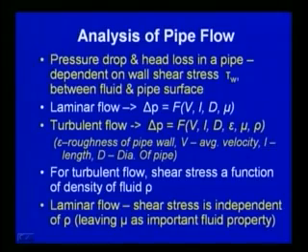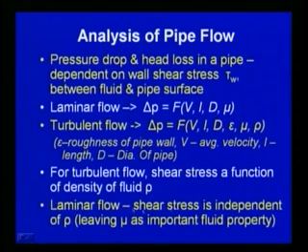We have to see whether we have to consider the roughness of the pipe wall, especially if it is turbulent flow. And also, with respect to laminar flow, the shear stress is independent of the density rho, but as far as turbulent flow is concerned, the shear stress is a function of the density of the fluid, rho.